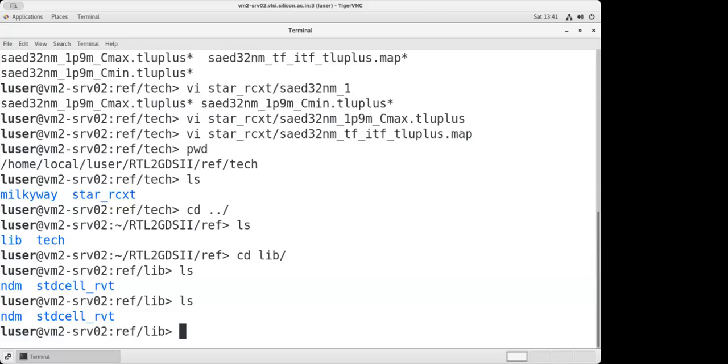So the question is, he has an understanding that as we go from metal 1 to metal 4, 5, the resistivity changes. That is his understanding. So it's not a universal rule like, okay, metal 1, metal 2, metal 3, they will have a different resistivity. That's not like that. There is a concept of metal stack. Maybe we will not go that far, but it's like you have an option. You can choose whether you need the metals for different resistivity or the same resistivity.